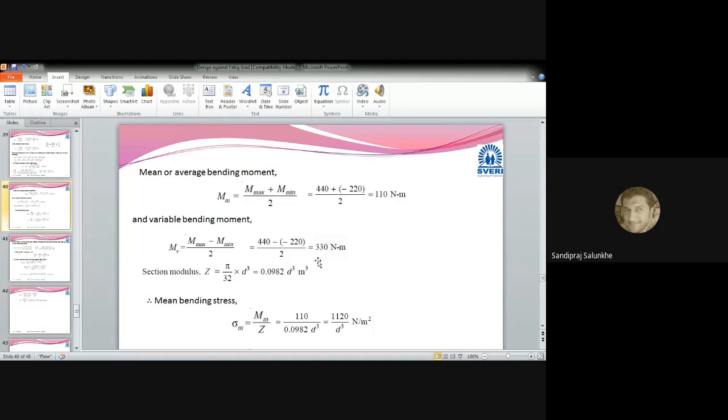Now this is about the shear stress. Now one more stress is also acting on that shaft, and that is bending stress. So that bending stress we have to calculate. That bending stress can be calculated from the bending moment, because we know the relationship, if you want to calculate the stress, M by I is equal to sigma by y is equal to E by R. From that we can calculate the stress.